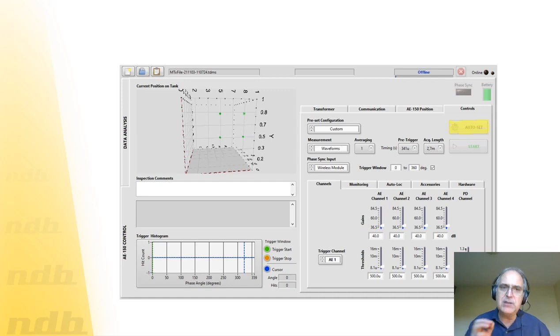On each position, you need gel, okay, the acoustic gel, and you need to set the gain. So each time you come to a new position, you need to key in the location XYZ, transformer, wall, side, and to reset the gain. Always, every position.